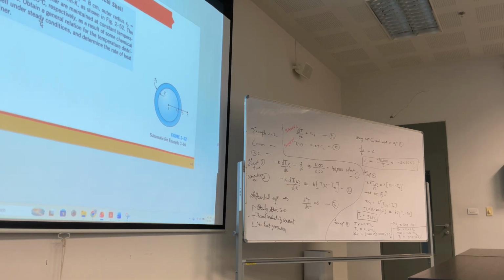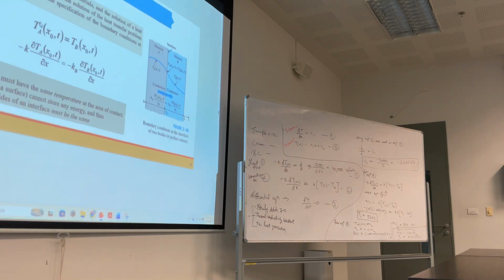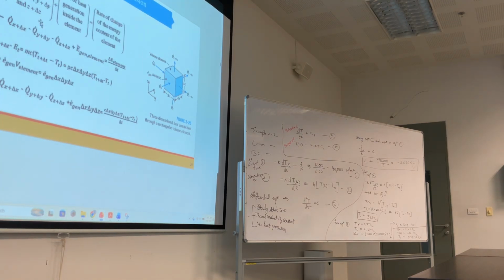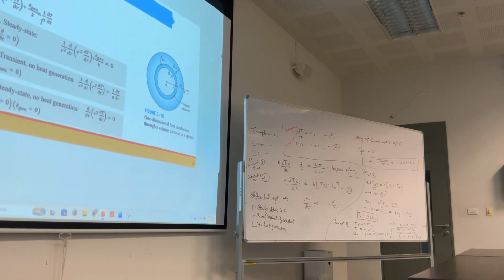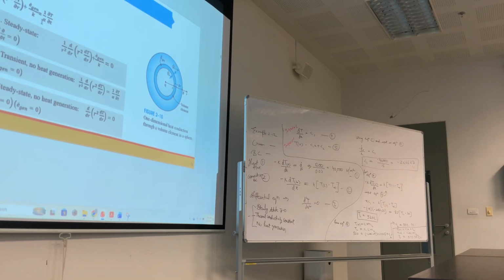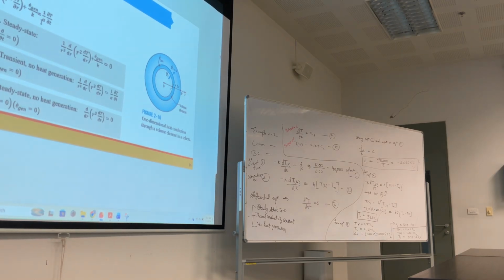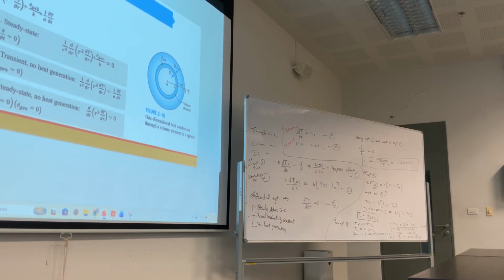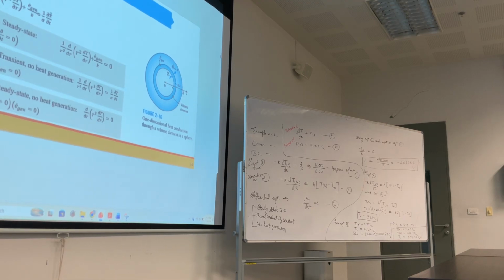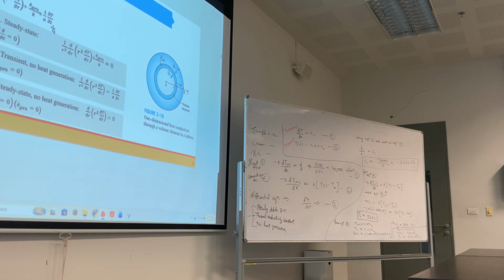Now tell me which differential equation for spherical. You have these differential equations. In that question, the thermal conductivity is constant, so we cannot use the first equation. This equation is not applicable. In that numerical, there is no mention of heat generation, and the temperature is also not changing with time, so we cannot use this equation.